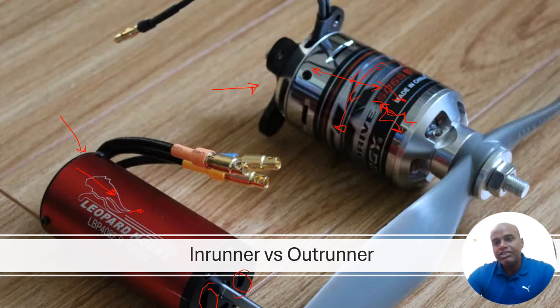So the heat gets pushed towards the shaft, and then it gets dissipated along the shaft through these ducts provided over here. Here it is clearly visible that the outrunner motor has more ducts, or bigger ducts, because it has poor heat dissipation.